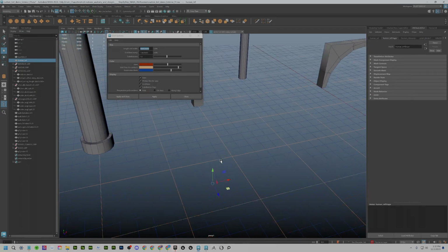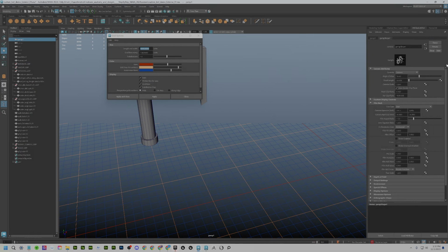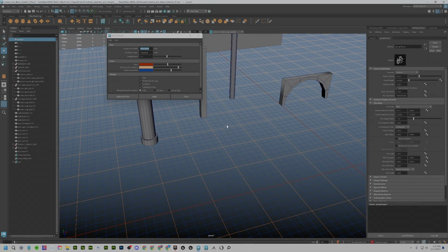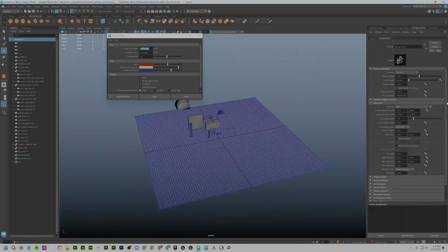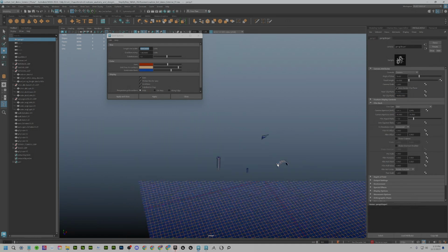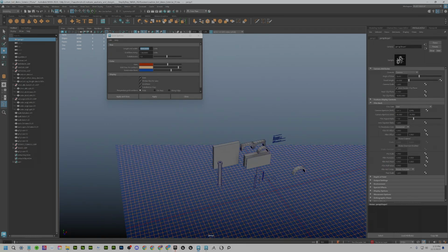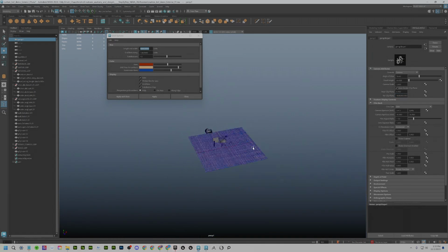When you start zooming in and out too far, you'll get a clipping plane that's really not very functional. So where's the default? I think it's right about there, but okay, that's not too bad. I forget what the default is now, but there we go. So right about here, it's clipping already. And then the near clip plane is also a problem. So I go to the far clip plane and I add a couple zeros in there, and that lets me zoom out just fine.